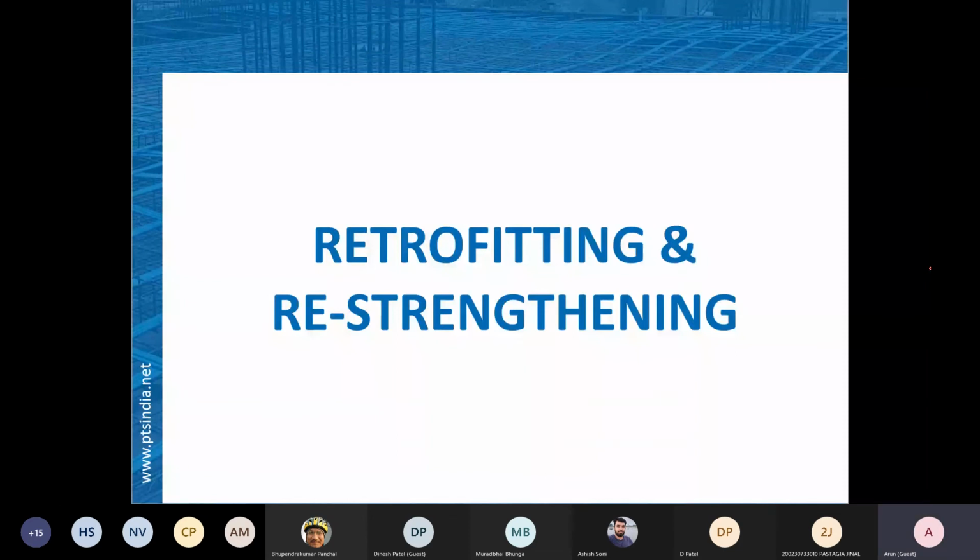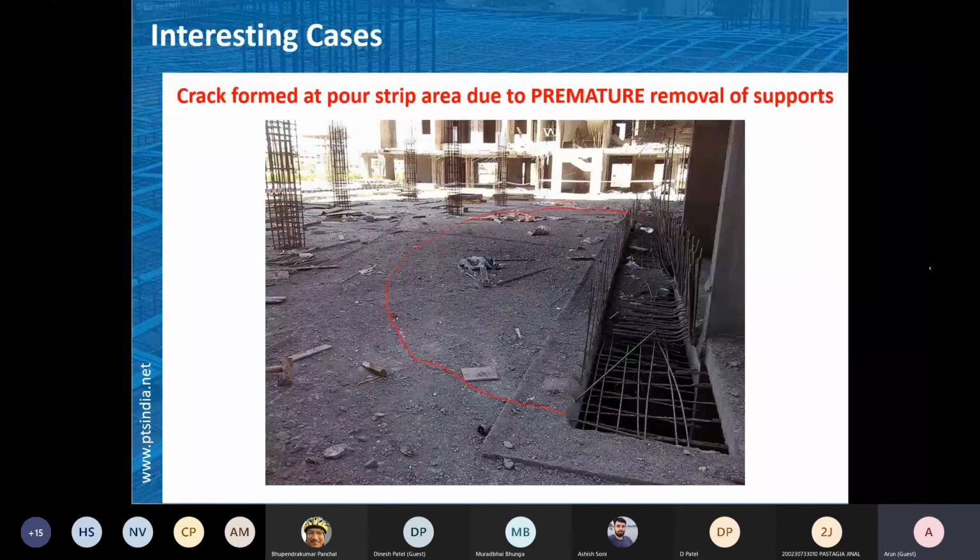Here, this is an interesting part. Generally, what happens is, in case of PT slab or maybe it is RCC, but still, we need to have a limitation in the casting. So because of that, we can cast a limited portion if the area is huge. So we need to define the pours, pour 1, pour 2, pour 3, like that.